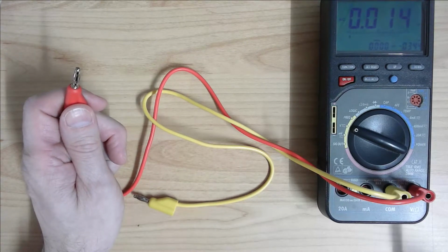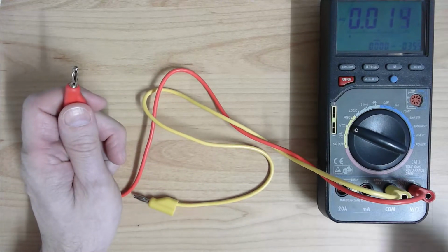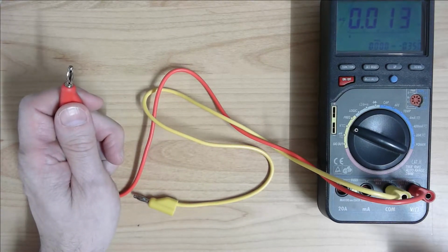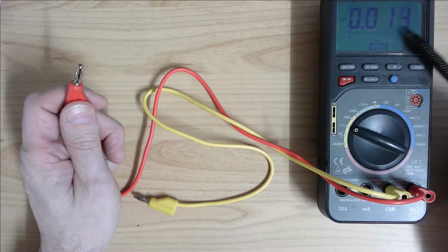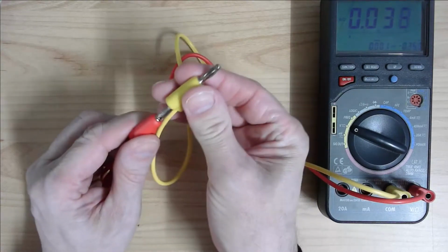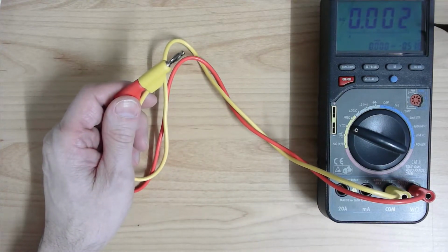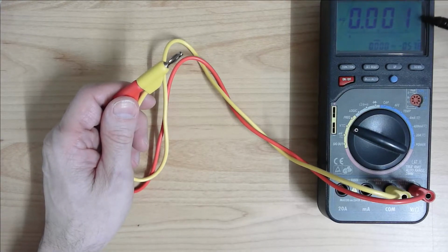We have a capacitive coupling to the power lines, and depending how far away the power lines are, we will see more or less a voltage here. This can be stopped very easily when we short the two lines, and we see that it goes back to the 1 or 2 digits of measurement error in the last digit of the measurement device.